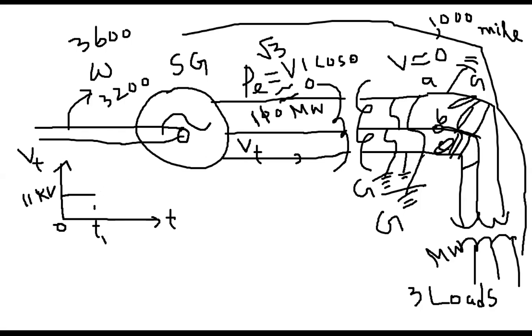And that fault, any of those faults that we discussed, 3LG, 3LS, 2LG, 2LS, 1LG, whatever the type of the fault, a fault happened, a disturbance happened, or a load change happened, and consequently, we are discussing synchronous generator, voltage will drop down first. And then I said it will oscillate. And after a while, it will settle down. Settle down means it will match with the previous situation.